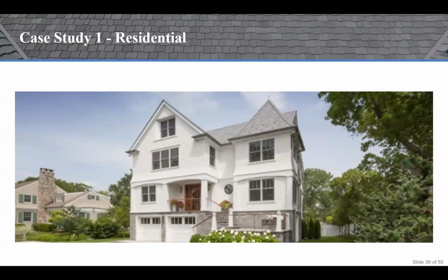The challenge was that this specific home was 300 feet from the Long Island Sound, so the home needed durable, moisture resistant, low maintenance products on the exterior. The solution was that it specified DaVinci Multi-width Slate roofing, because we've learned that composite slate resists salt air, sea spray, high winds, fungus, algae growth, insects, and termites. In turn, it became the winner of the 2017 Spec Home of the Year.